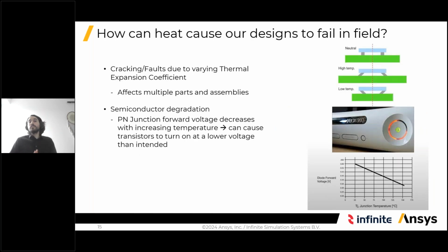More specifically, looking at the PCBs, the thermal expansion coefficient changing with the rise and fall of the heat causes very big solder joint fatigue. During temperature cycling, a solder connection expands and contracts, which after many consecutive cycles can cause degradation of the connection and thus failure of it. This lifetime behavior can also be predicted, and we will be talking about it in our last seminar. Today we'll be talking more about heat.